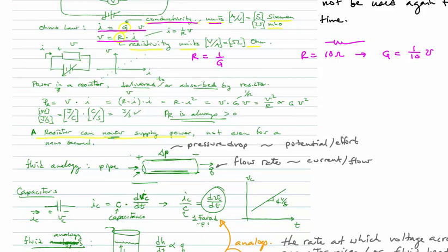So that's really all there is to a resistor. What else should I say? The power. We want to look at a little bit about the power going into a resistor. So we already know, and you can do the units check on this, that power is equal to volts times amps. Okay, so if you know the current through an element and you know the voltage across it, what effort it takes to push that much current, then you can calculate the power. Now, we can leave it in that form, but because we now have the VI, or terminal characteristics of the resistor, we can replace V with R times I from our Ohm's law, and we get power equals R times I squared.